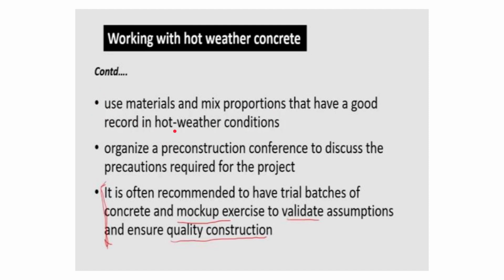Further strategies can be using materials and mixed proportions that have a good record in hot weather conditions, which perform much better as compared to the rest. And we can organize a pre-construction conference to discuss the precautions required for the project with the manager and all the concerned contractors and all the concerned people.